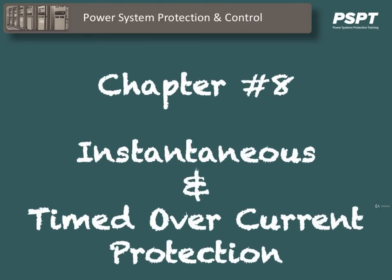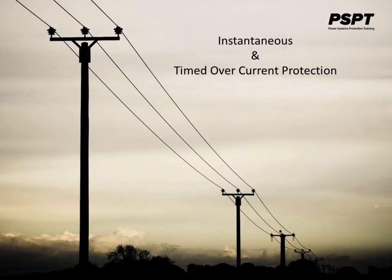Chapter 8, Instantaneous and Timed Overcurrent Protection. The next step up from protection by fuses and involving relays is a common one. It is the instantaneous and timed overcurrent protection. Primarily it is used in feeder protection because long feeder lines lend themselves very easily to being coordinated by inverse time overcurrent or instantaneous protection.